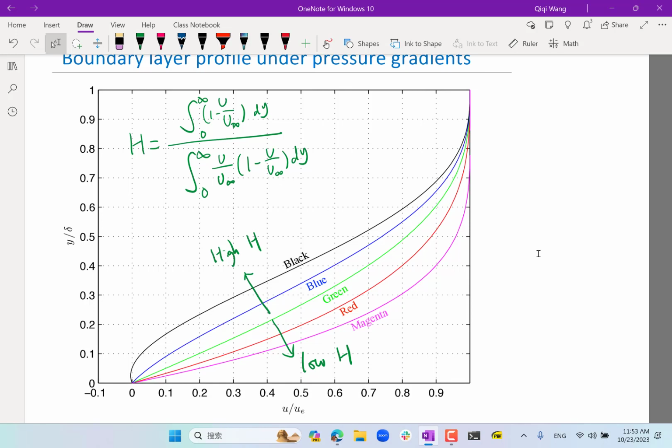So as long as we have an opposite curvature, like what we have over here, the viscous force actually drags the flow forward. When the profile has a curvature like that, the viscous force drags the flow backwards, right? As in the pipe, and you're going to do the pipe in homework, right? As in the pipe and the channel case, with a negative curvature, viscous force drags the flow backwards. A positive curvature, the viscous force drags the flow forward.